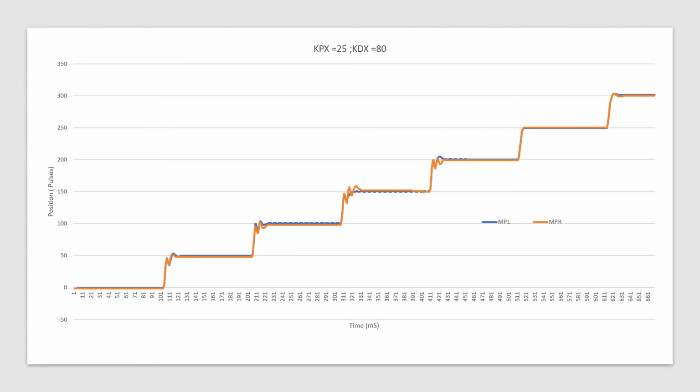Here we have the PD controller. This is a PD controller after it has been tuned and the derivative factor has been applied. The transient response time has decreased, and the overshoot has been drastically reduced as well. Well, because it attenuates the high frequency, and I was able to increase the gain by a lot since the step input has reduced to 50 pulses, and the KP is 25, and I also increased the KD too much. The only downside is that this may be overdamped.